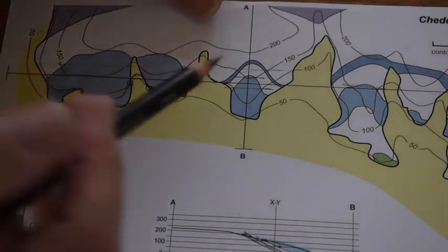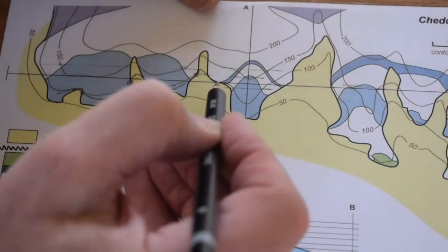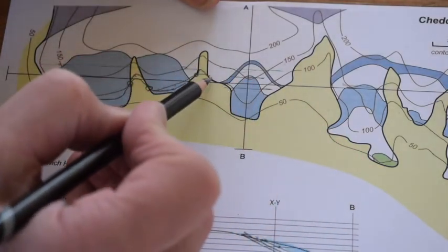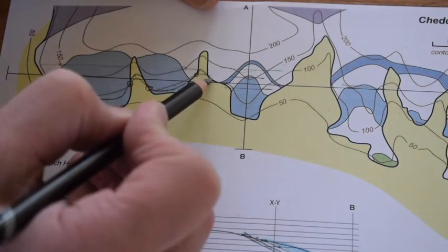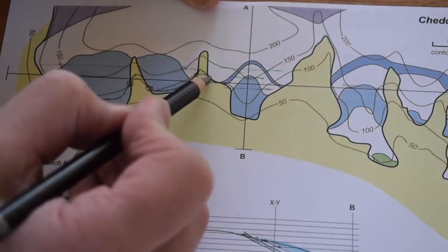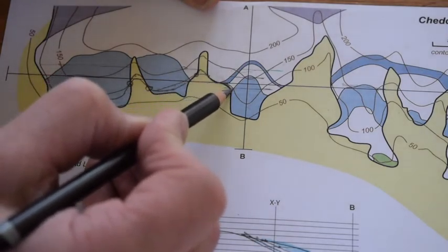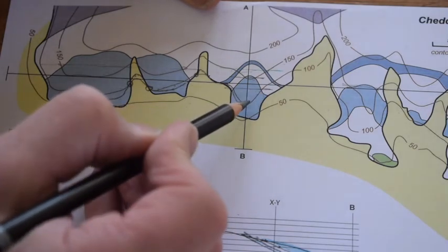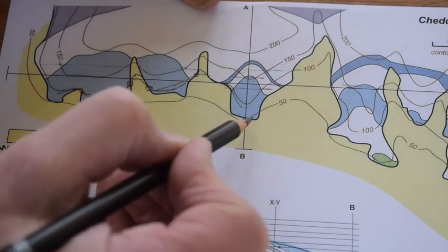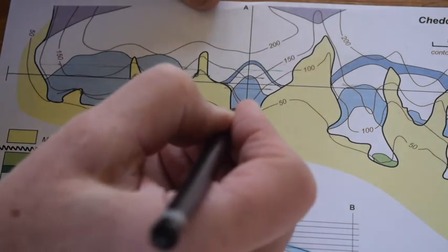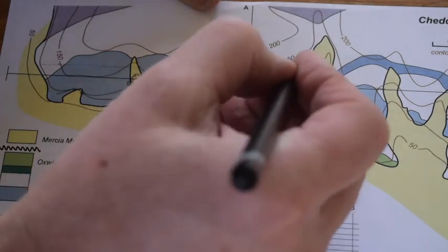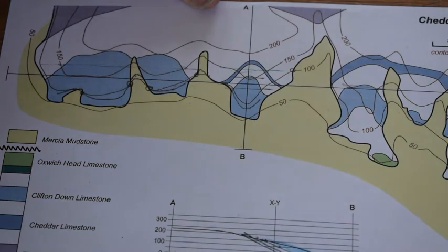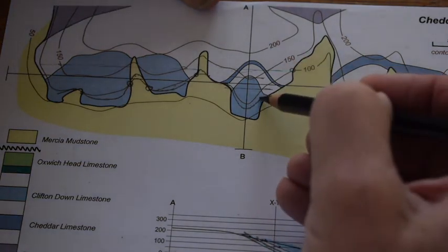Let's keep it going. So we've got our structure contour coming to here. In this position, the topographic contour is more or less on the boundary, so it actually is also the structure contour. And then it's going to emerge through here, around there. It must be constrained by the 100 metre topographic contour and the outcrop of the unconformity. So it's going to come round through here like that. It's heading for that point. So let's keep it going. It's going to go through like this,